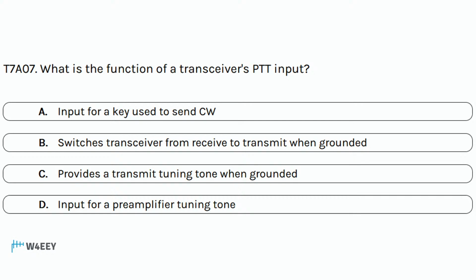B. Bravo. So PTT stands for push to talk, and I probably didn't mention that. But yeah, it's two wires that come out to a switch. Maybe it's in the microphone, and when you push that down, the two wires short together, and what it's really doing is grounding a signal control line, and that will take the radio from receive to transmit. Push to talk.